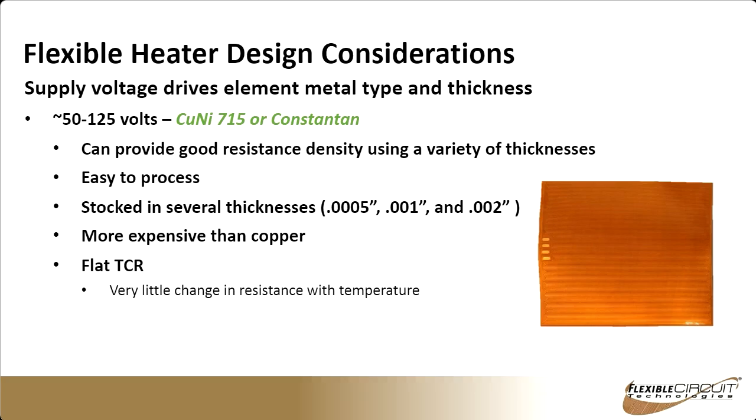Mark, a couple questions. First of all, do we care if it's AC or DC? The heater doesn't care one way or another. Either one of them is going to produce heat. One thing to keep in mind is that if you're using AC, you're putting AC into an antenna. And so if you have other electronic devices in close proximity, it might really drive them crazy.